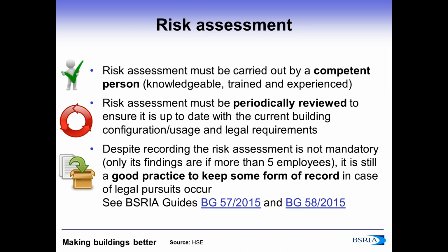This risk assessment must be carried out by a competent person. This person doesn't need to have a particular qualification or diploma, but must have sufficient knowledge in the risks associated with Legionella, be educated to understand what could happen, have attended some form of training, formal or informal, and have some experience in performing risk assessments within water systems in buildings.